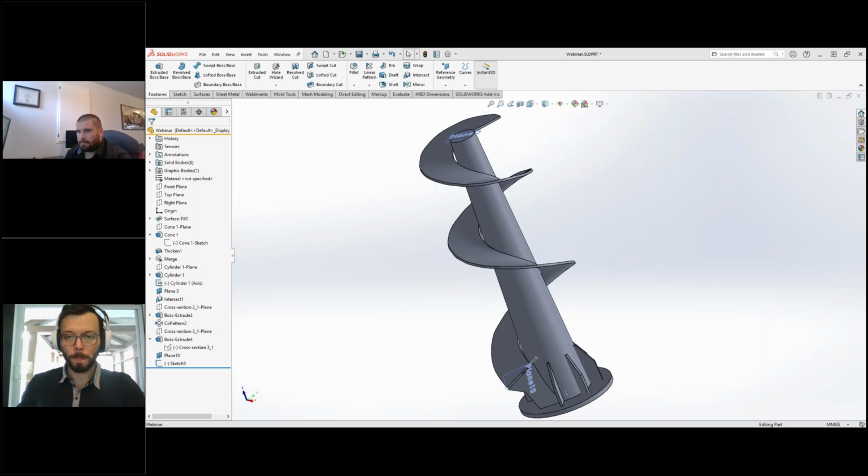Great. Another question here. How far is the distance that the scanner is from the part while scanning? And this one I can answer. So the usage distance with a PL3 is between 250 to 550 millimeter. So that's 9.8 inches to 21.7 inches. Reference distance is roughly in the middle. So that's around 400 millimeter, around 15 inches or so. So these are the reference distances.